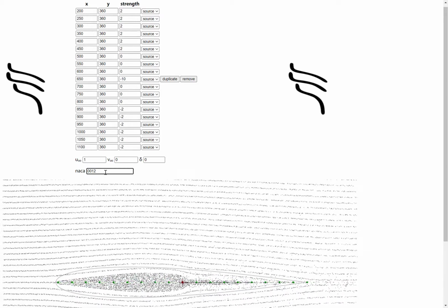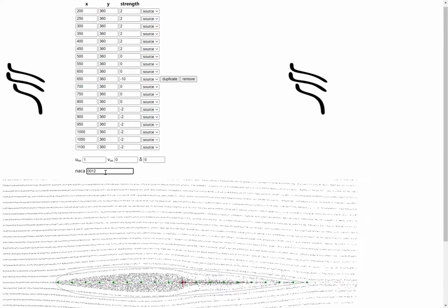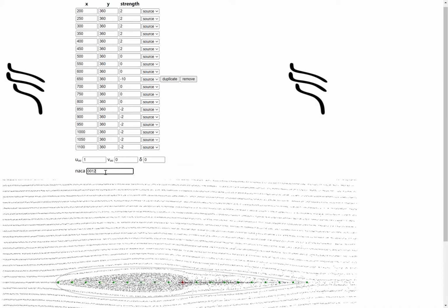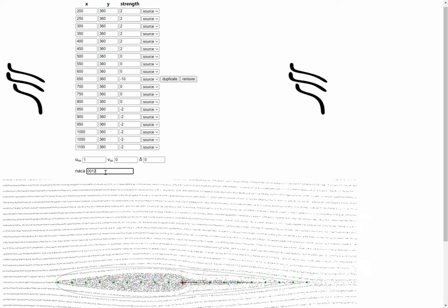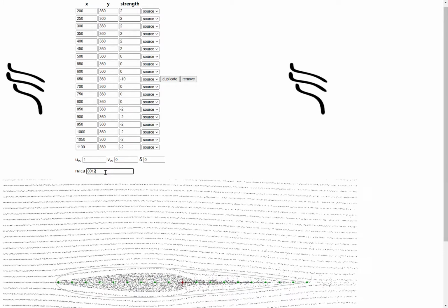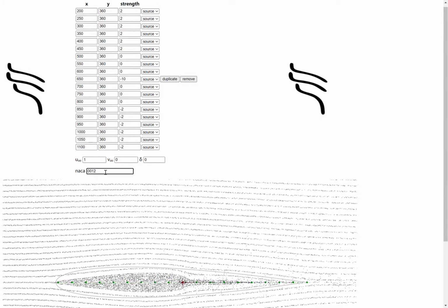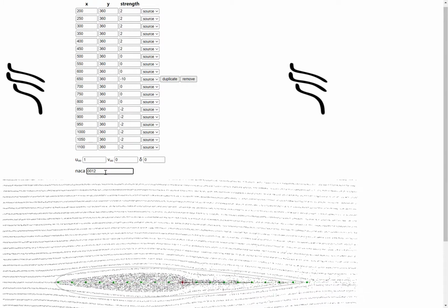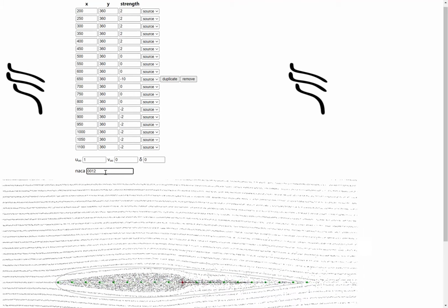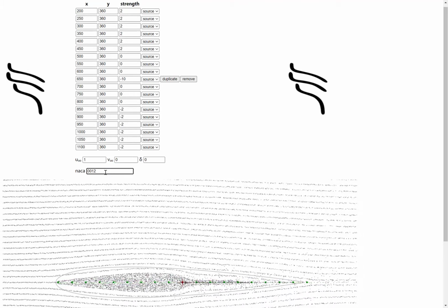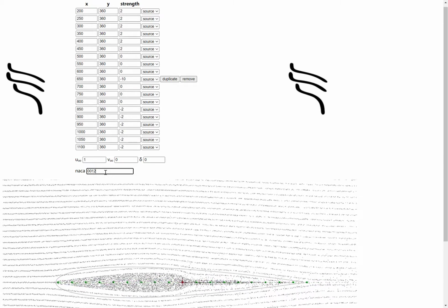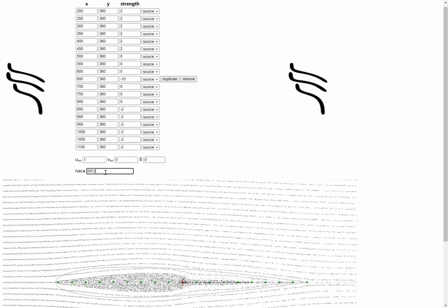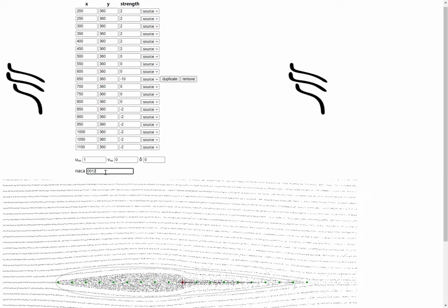All right, I'll give you some time to do that. Do you understand what principle we are using? We are not changing the strength blindly. We are using the principle that you put a positive source if you want the airfoil to thicken in its neighborhood, and a negative source if we want the airfoil to thin out.